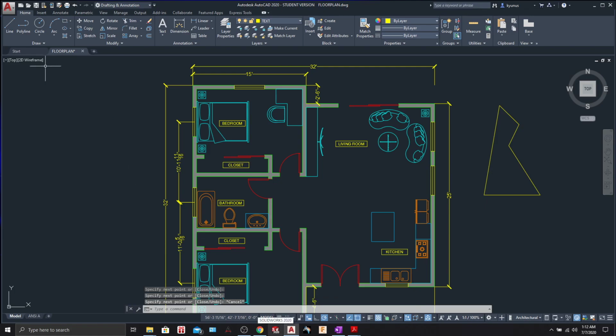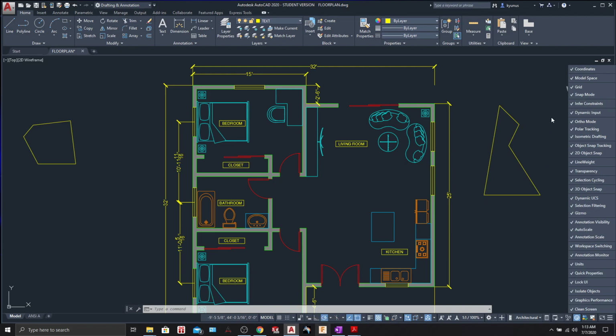And if I switch it on and now I take a line, it's a guided access kind of thing going on. So it lets you see what's going on when you are drawing any sketch. Even if you are modifying or doing move or copy, this dynamic input helps you a lot. So I'll talk about it later in detail.